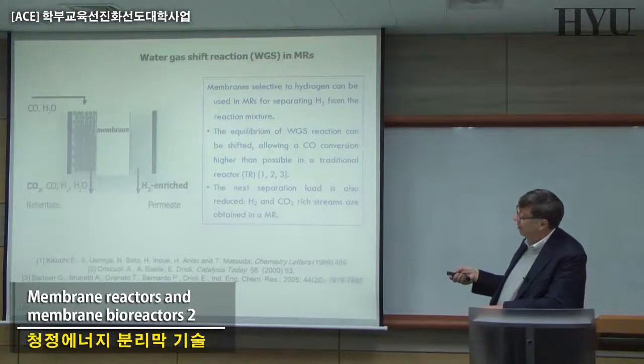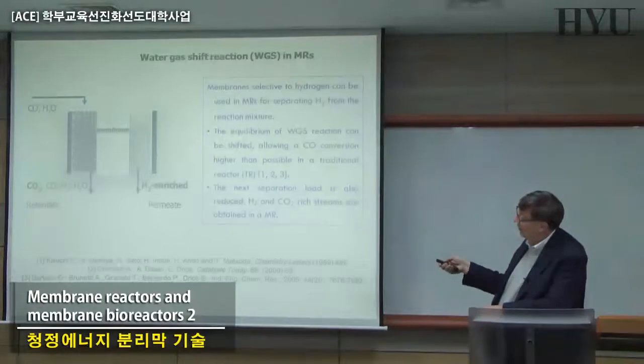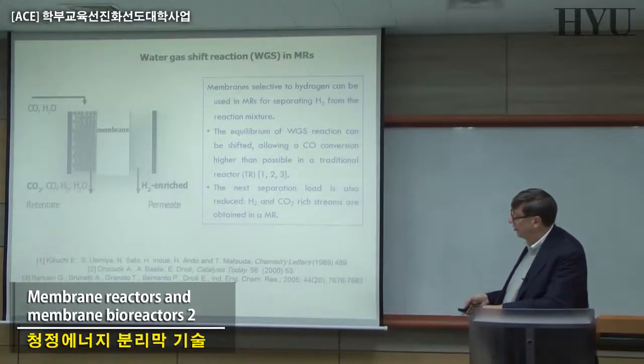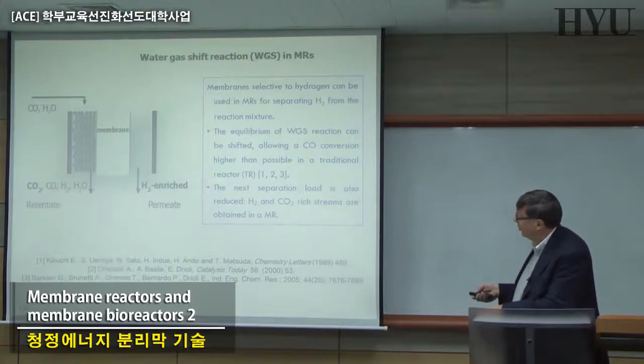That is the situation that you have in membrane reactors. The CO and H2O are converted in the catalyst bed, and the retentate is basically CO, CO2, hydrogen, etc. And if these are the appropriate membranes, enriched, pure hydrogen is what is coming across your system.